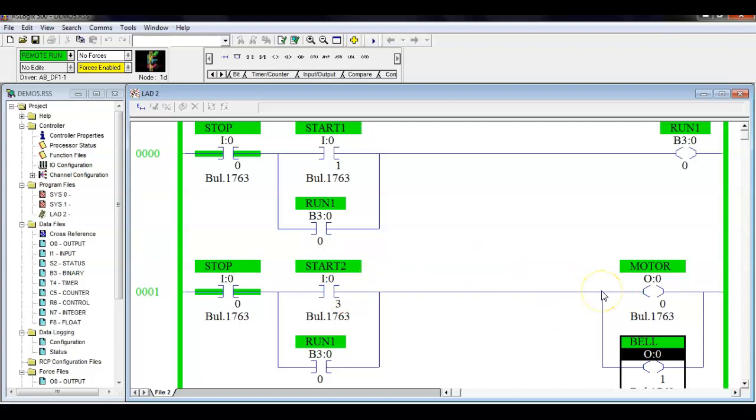If I use this one, then this is, anybody know what jogging is? What's jogging? This is when we run motors in bursts. We don't want them to run, we just want to move it so far. We use this for positioning. So when we go over there and we move the robot, we call that jogging. So if you're taking the robotics courses, you get that teach pendant and you're manually moving the robot with those buttons on there, you're jogging the robot.